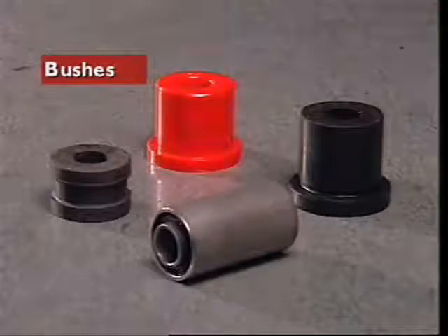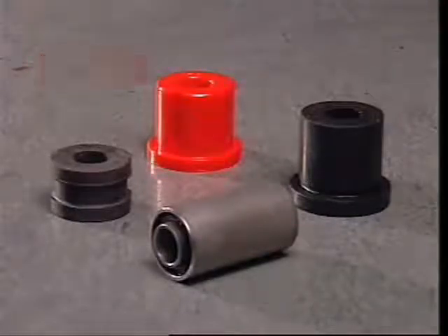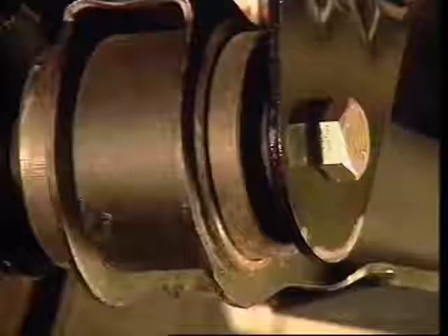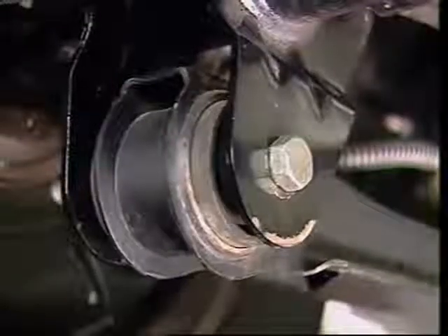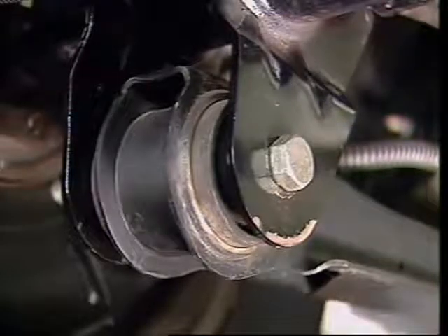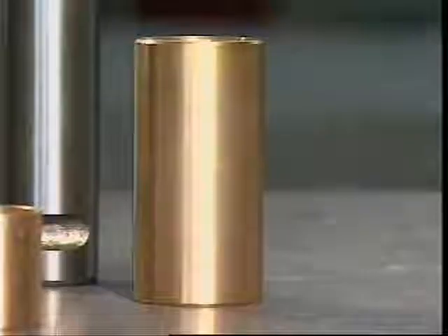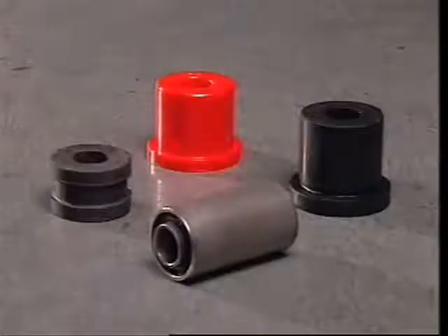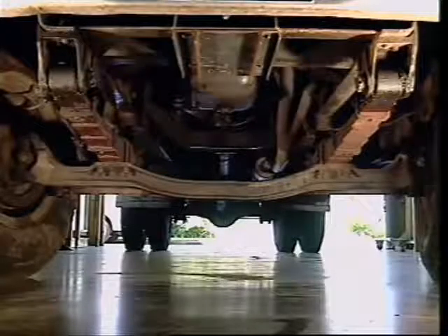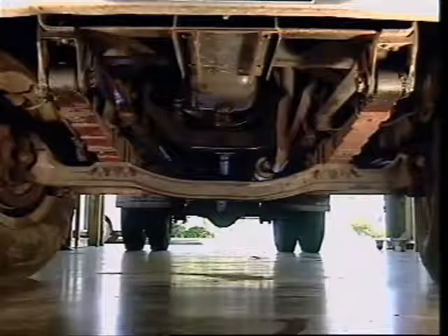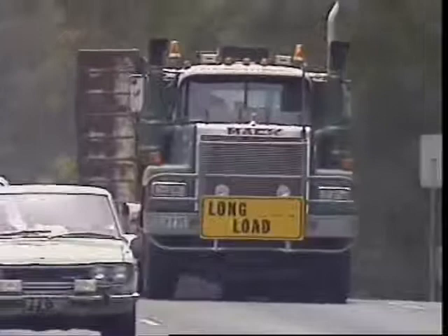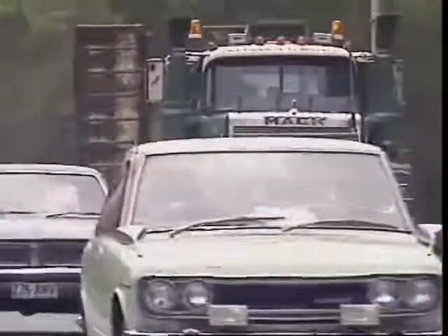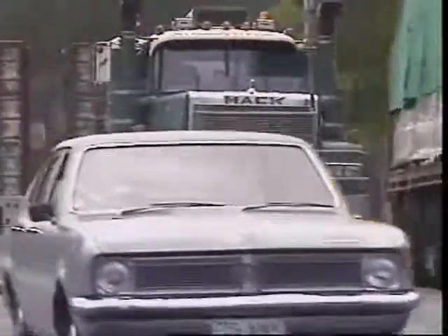This section examines suspension system bushes. Bushes act as bearings at suspension fulcrum points to allow for movement of the component while maintaining its alignment. They can be metallic or made of rubber, nylon or urethane. In commercial vehicles, metallic bushes are commonly used as shackle bushes for leaf springs. Any force applied to the bush acts through it to the body of the vehicle, which results in a harsher ride.